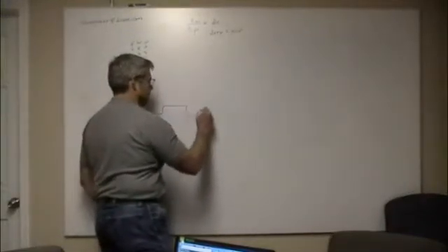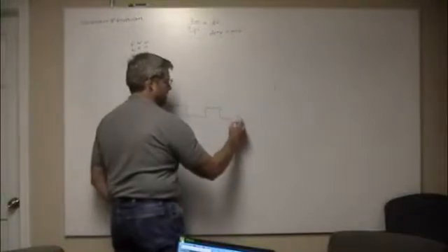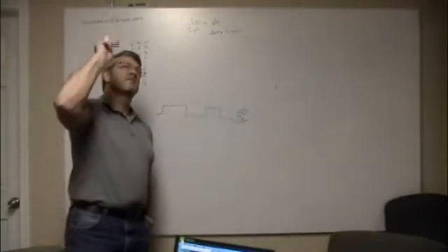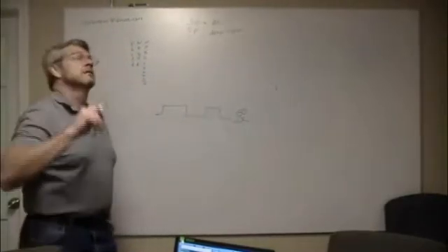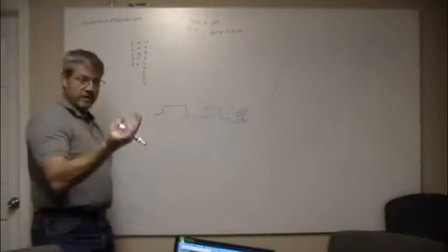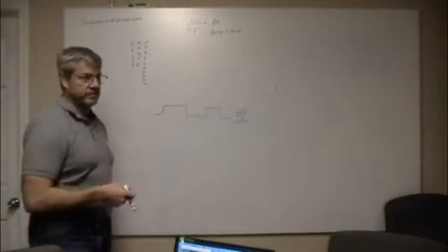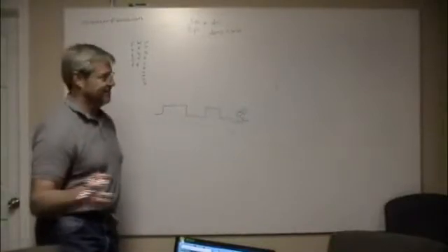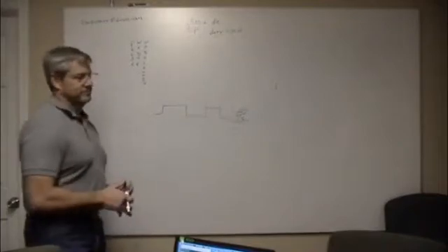So the last thing is we can PWM an LED, or even, you can't do a fluorescent, I don't think, but you can do a regular tungsten incandescent bulb. They'll do it, but you'll start to hear them sing after a while. So you need to choose a frequency that's high enough that you can't hear it. So many kilohertz.